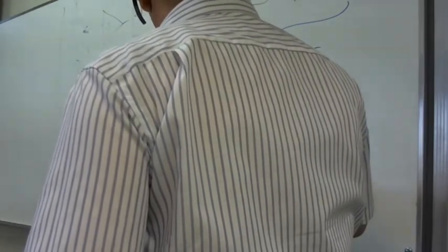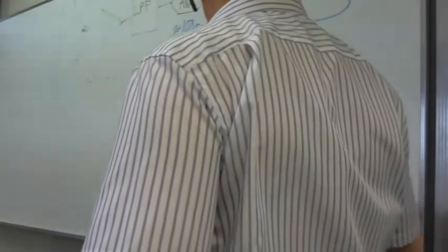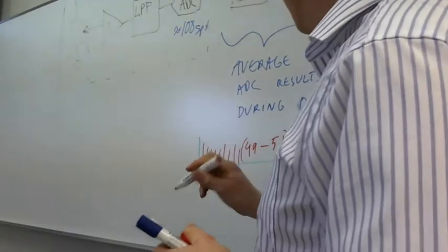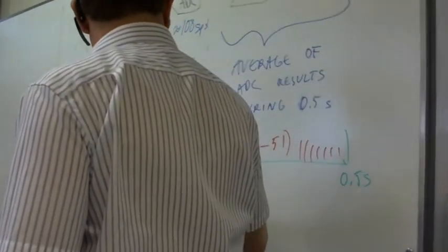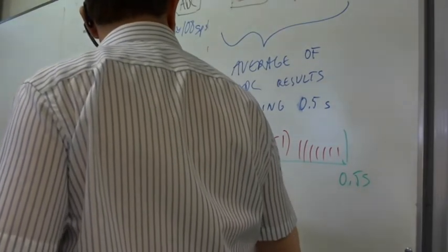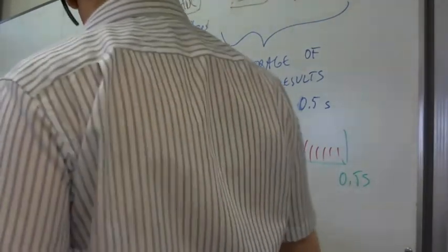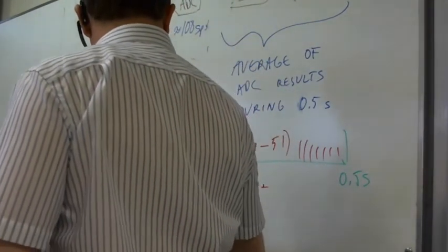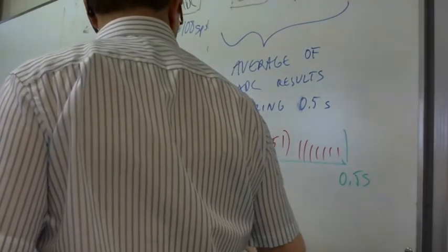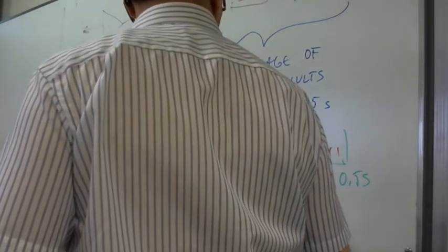So anything between 49 to 51 samples here, which means that in your software you need to have a sample count value that you will increment, and then you would have the ADC sum that you will increment by the step of the ADC value.